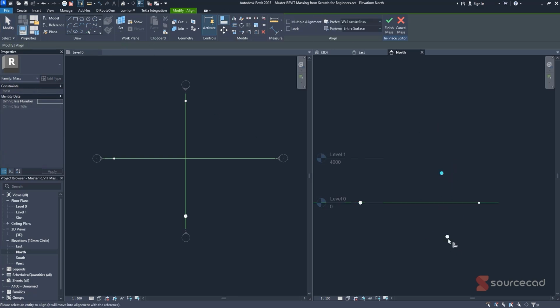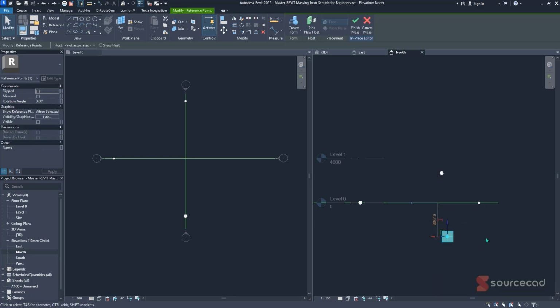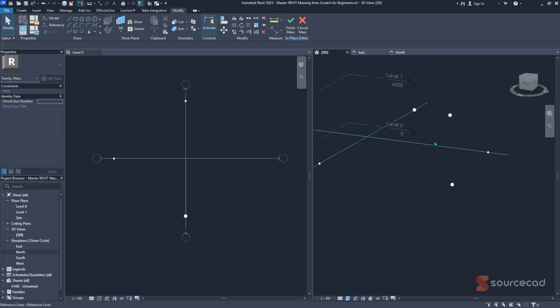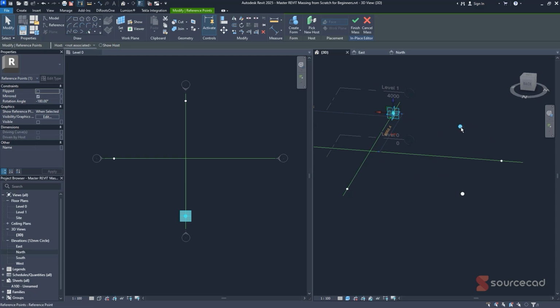And then once that's done, it's just a matter of eyeballing it. Just making sure that we have something of the sort. It's not a must for it to be perfectly aligned, but something like this will be satisfactory. After that, it's just a matter of selecting our point elements. So I'll select the first, the second, then the third. Then I'll simply use this option, which is spline through points.